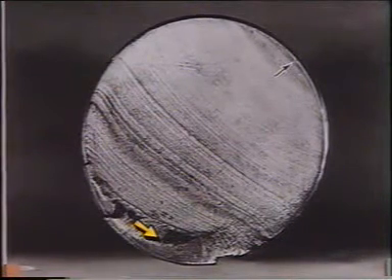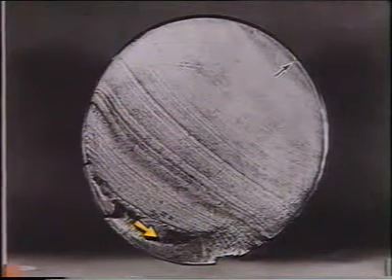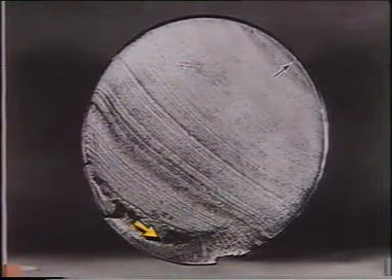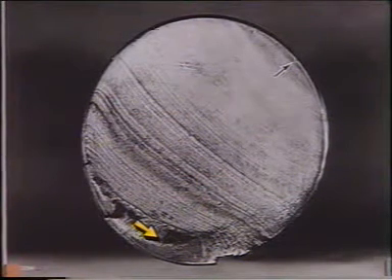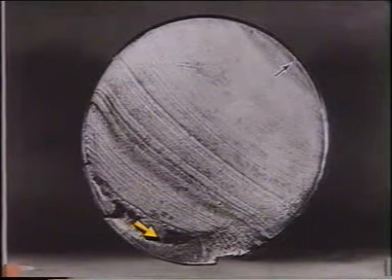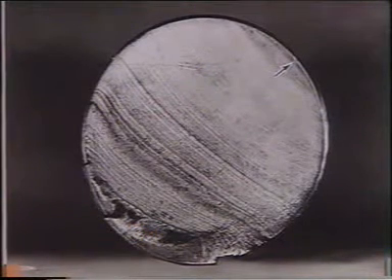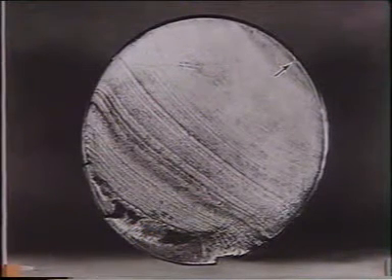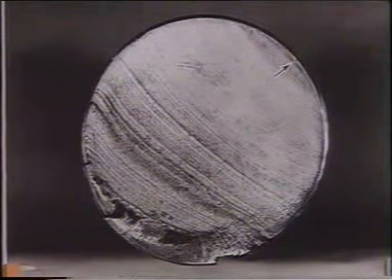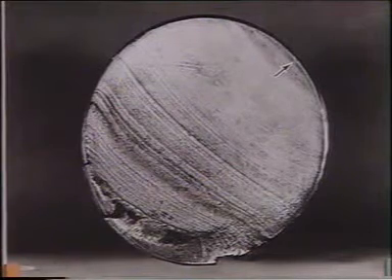The importance of stage 3 in the analysis of fatigue fractures lies in the observation of the size, shape, and location of the final rupture. Size, shape, and location help identify the type of stress, its direction, the relative stress, and the strength of the metal in the part. This is a bending fatigue fracture of a large threaded shaft. The fracture began at a groove on the surface of the shaft. The beach marks indicate that the fracture proceeded almost entirely across the section before the final separation.